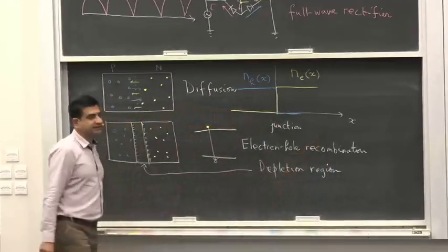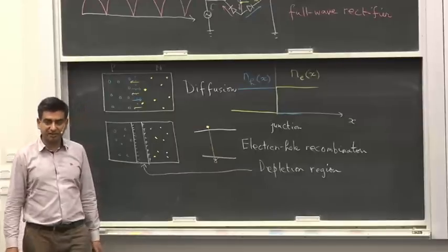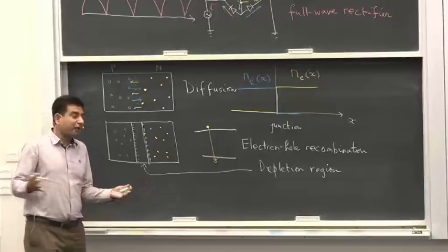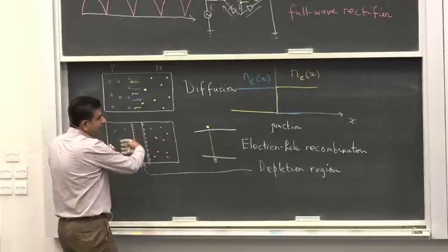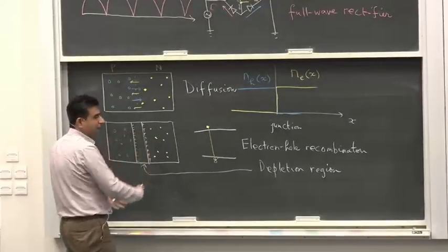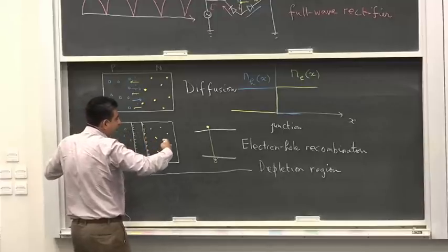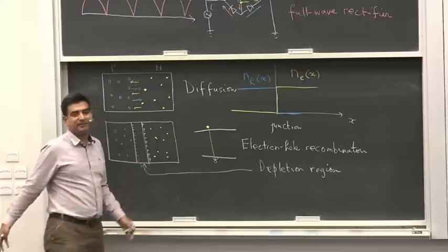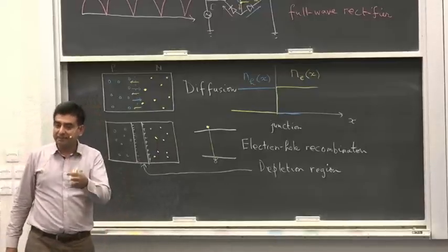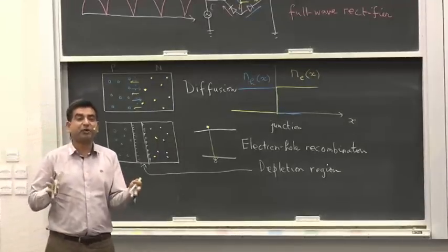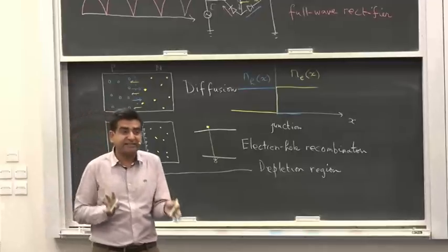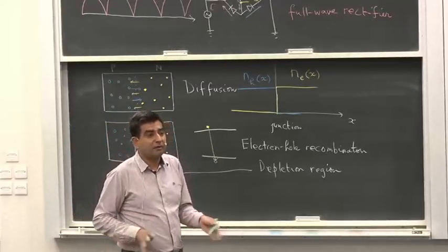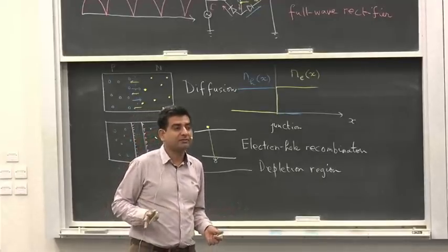And this effective capacitor is called a junction capacitor. Now will this process continue forever? If it's going to continue forever, all the electrons and the holes are going to interdiffuse, and this entire region is going to grow with time in space, and all of this will become the depletion region. But is there a limit to this? When will this process cease, if it ceases at all? Is this process going to stop somewhere, or is it going to carry on forever? What do you think?